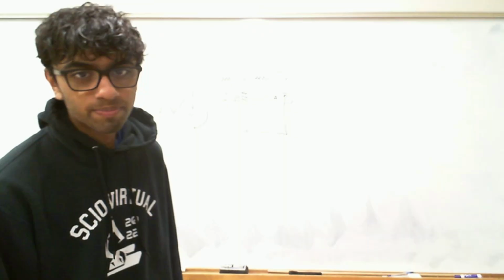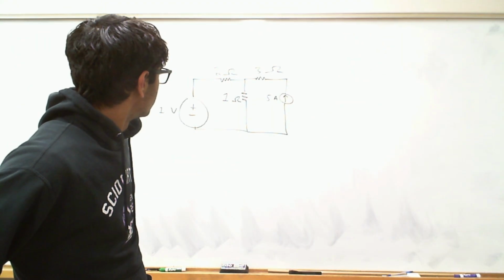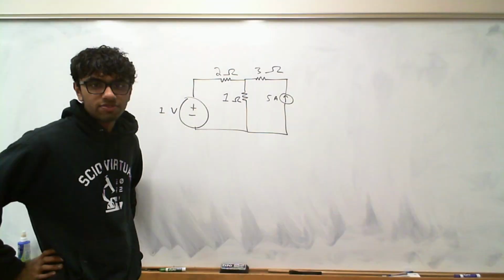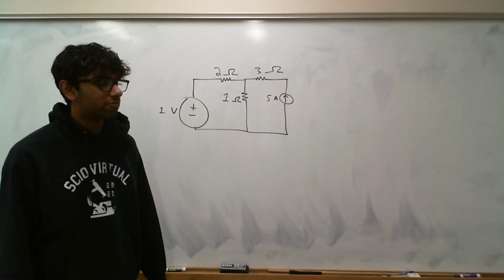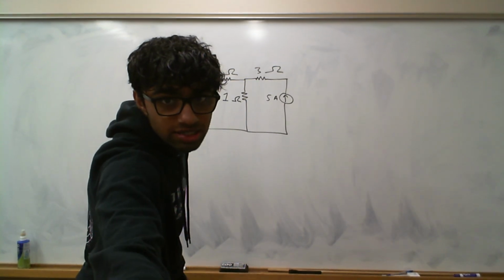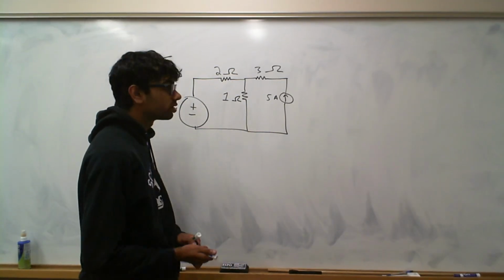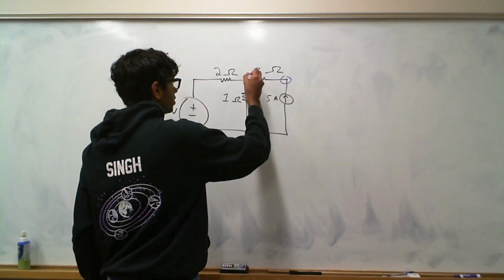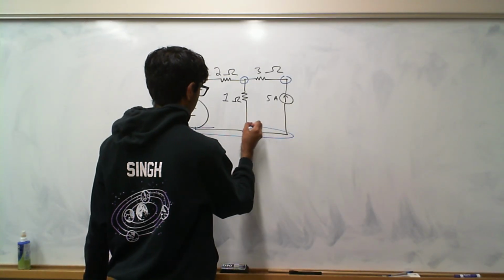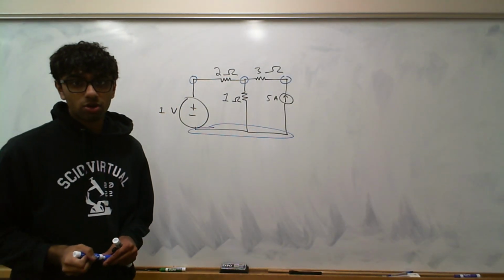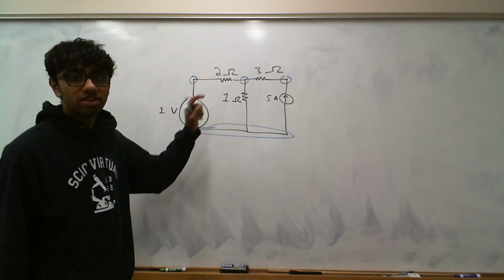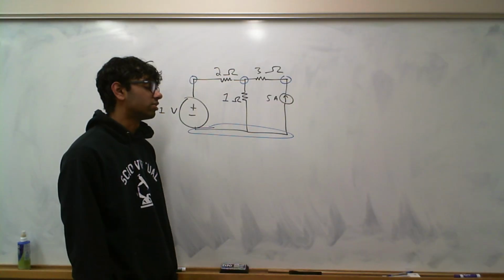Okay, so our first circuit is this guy. Basically, a very simple application of nodal analysis and what we've been doing. First task is to identify all the nodes. There's a node here, node here, node here, and all this right here is a node. Remember, nodes are the places where connections between elements exist. This is only one node, even though it connects more than two elements together.